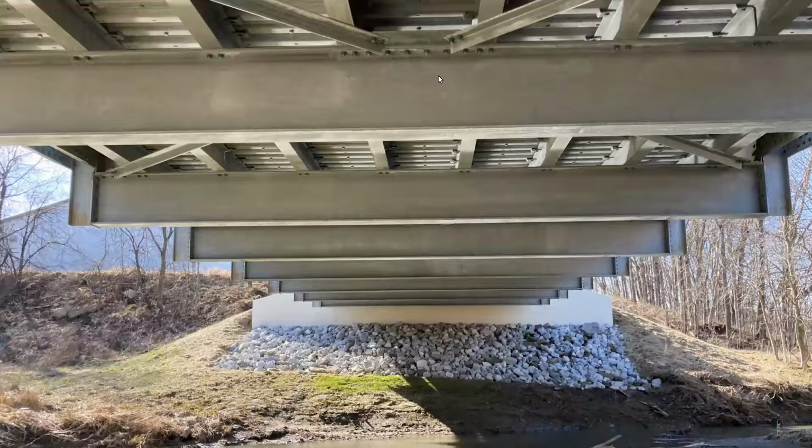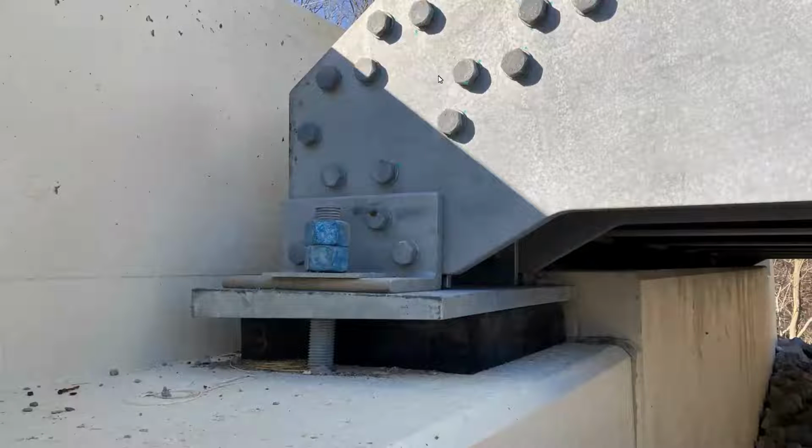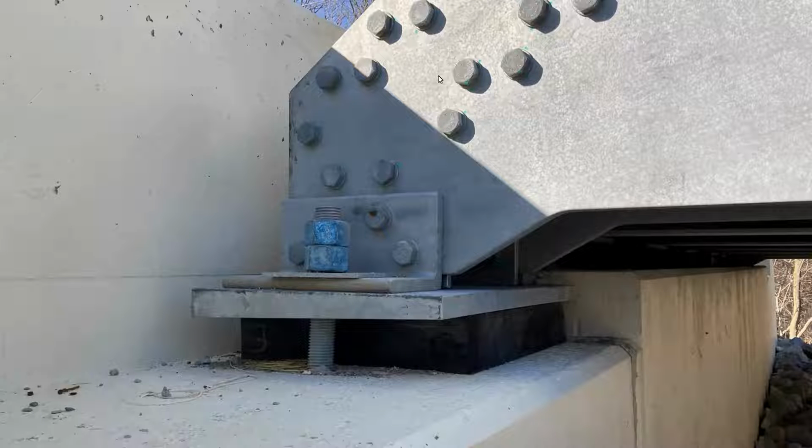You can see here that the steel floor is laid flat and clipped to the stringers. And again, the concrete is contained with edge dams and screeded off with a power screed. Here is a close-up of the laminated elastomeric bearing pad and the stringer seats beyond.